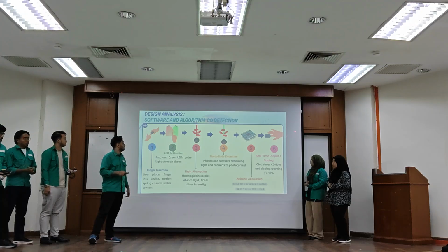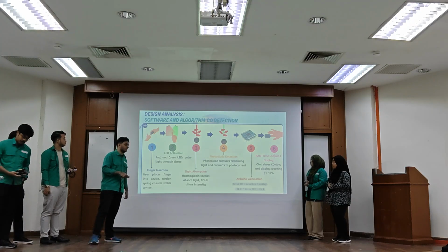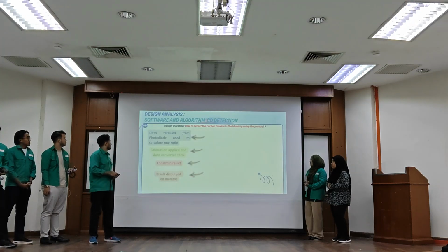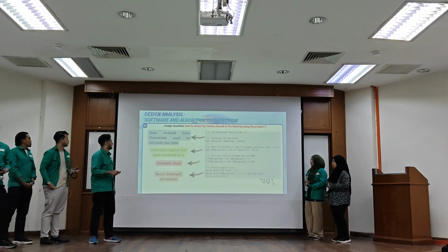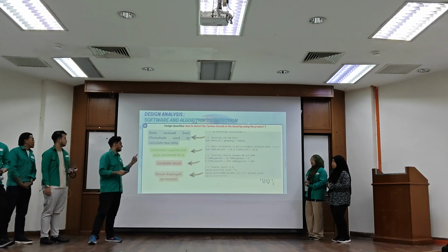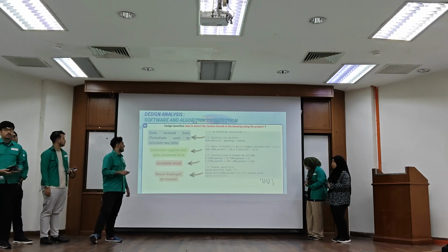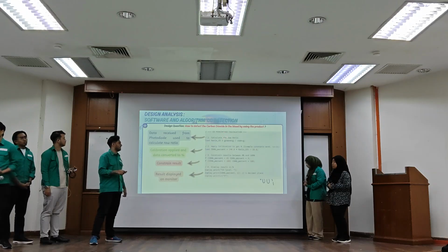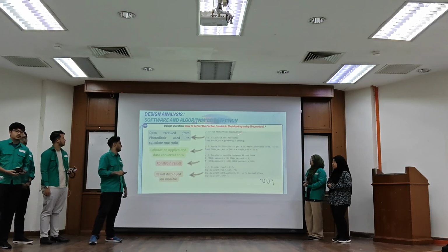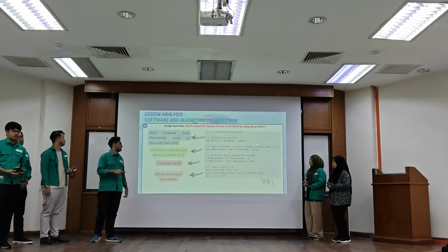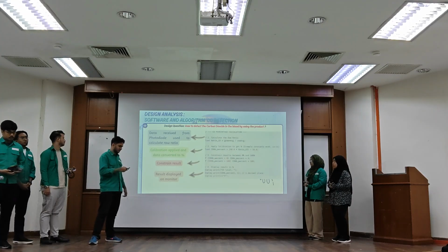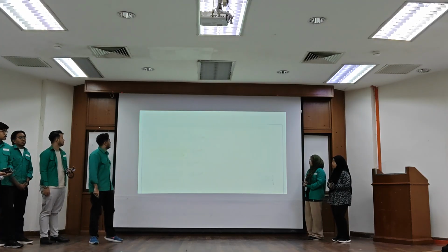From this we can get the percentage of carbon monoxide. Here is some of the calculation. After the light travels through our skin, the photodiode receives the average green reading and average red reading. From that, we get the ratio for carbon monoxide, and we do some calibration to get the percentage.